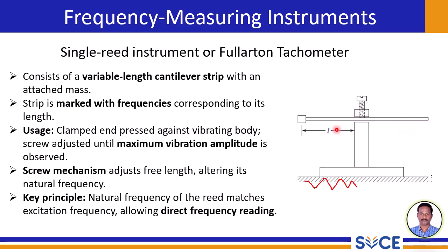Usage, it is well known. We have to clamp the end pressed against the vibrating body. The screw is adjusted until maximum vibration amplitude is observed. The screw mechanism is very important here, to adjust the free length, in such a way that we are altering its natural frequency.